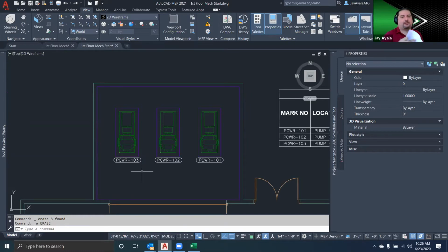The next topic that we're going to talk about, guys, is the property set definitions. Now, the property set definitions, these guys are the heart and soul of what is happening with the tagging capabilities and the schedule capabilities. If you're not familiar with them, and this is your first time looking at it, I want you to know that I'm going to show you a basic set here. And I'm even going to do some automatic and some formulas. However, you can get really creative with this and make any kind of algebraic formula.